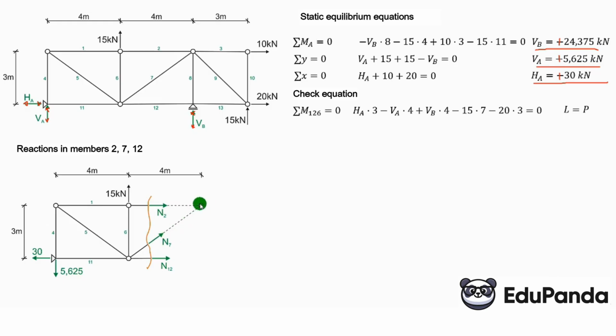At this point, the forces N7 and N12 converge, these two unknowns. So when we sum the moments at this point, I might label them point 1, point 2, and point 3 here, so we will also do it in such an order. When we sum the moments at point 1, then N2 and N7 pass through, we directly calculate N12.